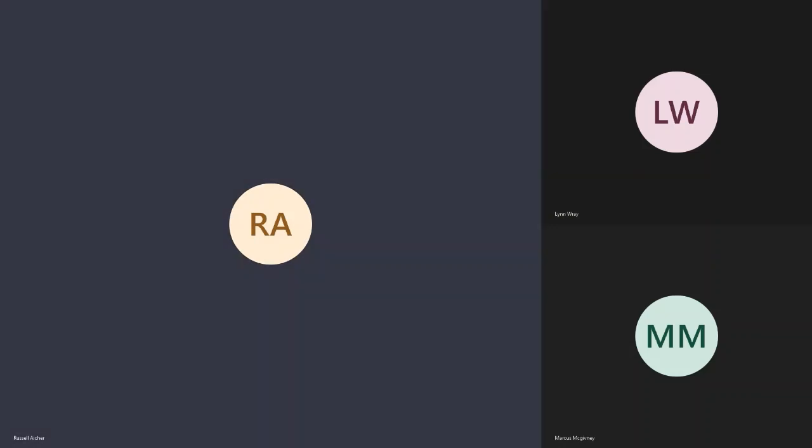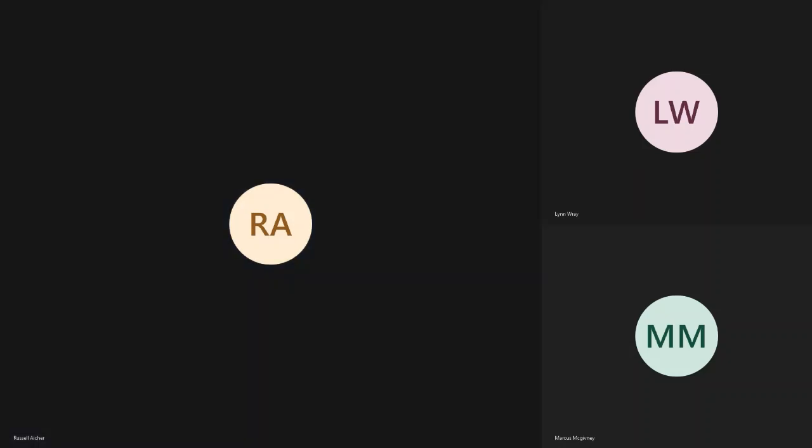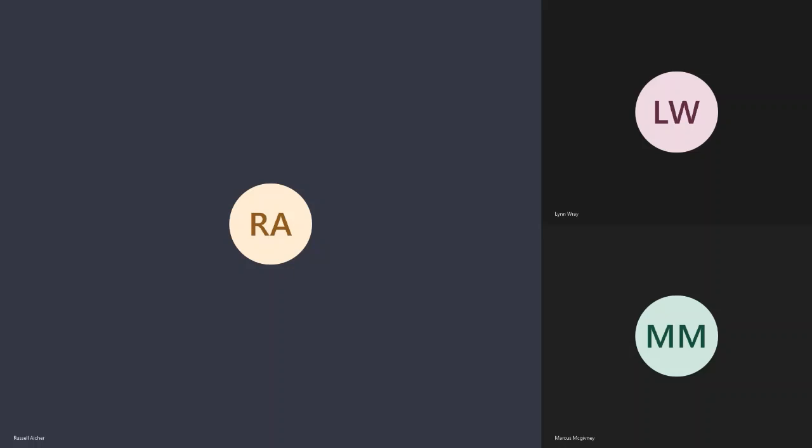The best example I saw of this, somebody was working on trails they had downloaded from the DEC from New York State. And there were a couple places, I don't know how they created them, but you could definitely see a zigzag in the trail. There was no zigzag in the trail in reality. Somebody goofed in the digitizing, or more likely there was an error in their GPS, like they lost lock or something. Because that zigzag of the trail, they were within a couple meters of each other. So it goofed. Setting topology will fix that. Okay.